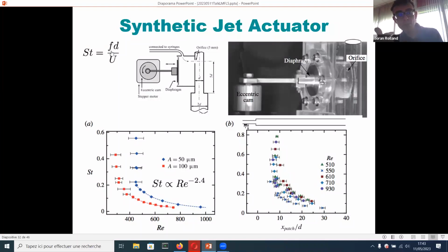And this has also been done non-linearly, trying to find the most responsive initial condition that would trigger the maximum amplification in full Navier-Stokes equations and all these kinds of things. So maybe this kind of criterion of disturbance or forcing of a very wide class could help identify some typical routes or paths to turbulence and their forcing.